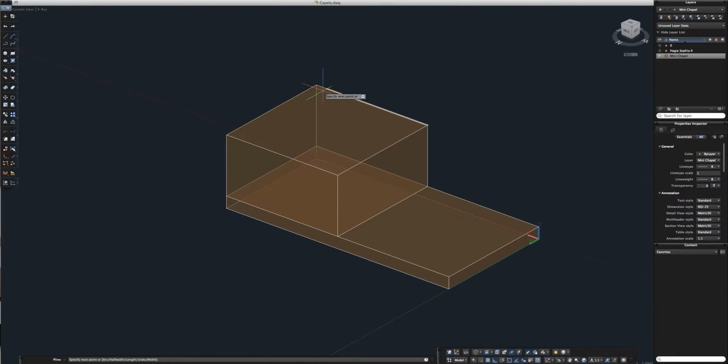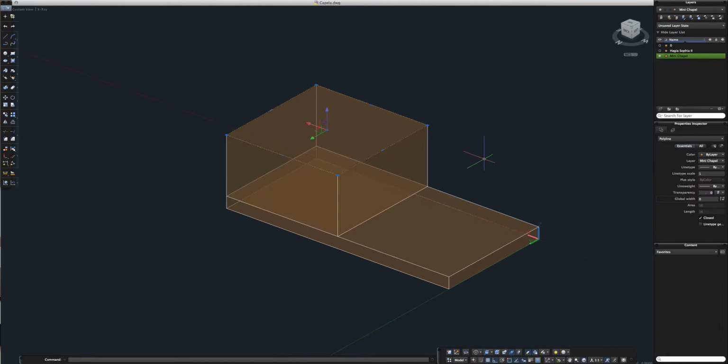Yeah, I can do this with an offset. Let's just draw around our cube, then close this polyline. Just going to turn on the width. Okay. Now let's make an, my bad. Let's make an offset. I'm gonna make an offset of about 0.4, just like the slab's width.